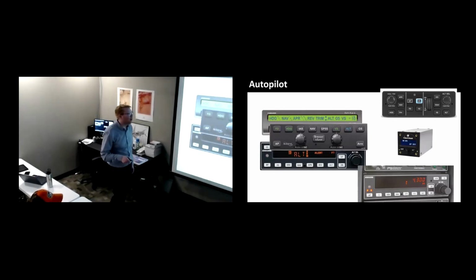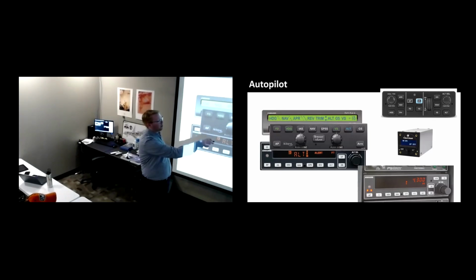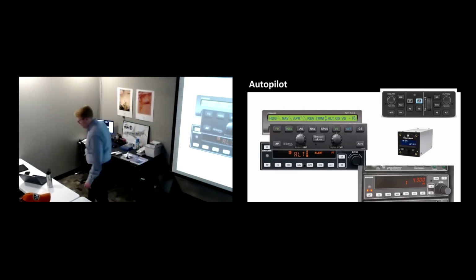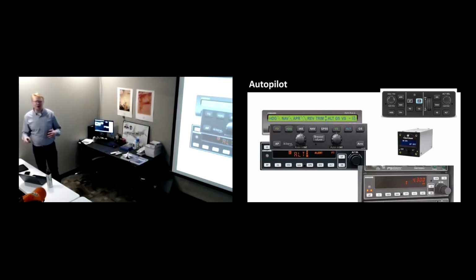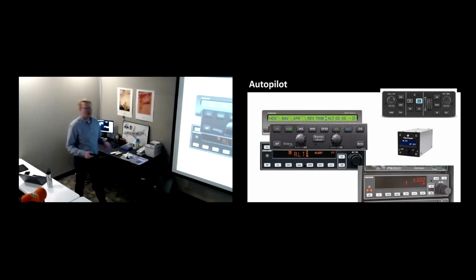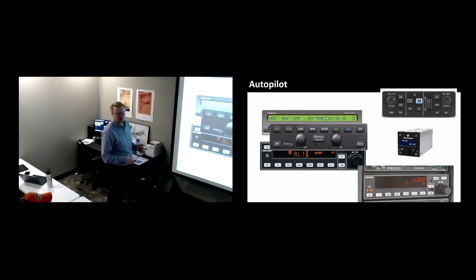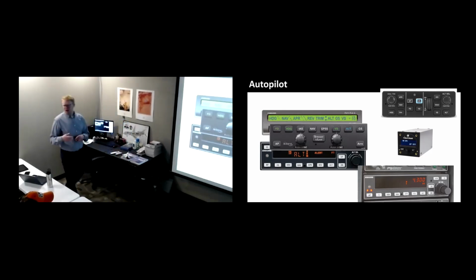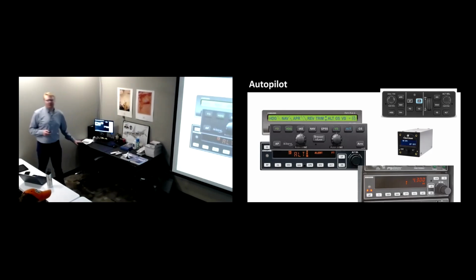Whether you're using a Bendix King autopilot, these Garmin GFC 500 autopilots are really sweet. You can do a ton of cool things like select a heading or fly an approach or navigate to somewhere, a particular heading, or vertical modes. Like I can climb and descend at certain rates or maintain an airspeed or descend on a preset path. I can maintain an altitude. A lot of cool functions these autopilots can do. And they all work by adjusting the control surfaces through some form of servo. Now, more fancy airplanes aren't adjusting those servos as much as they are adjusting computer inputs to hydraulic systems. That makes sense? Autopilot's not necessary, but we do like it.